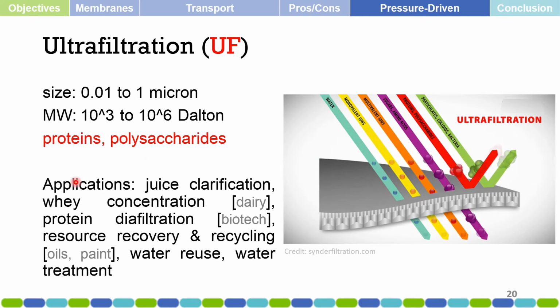Since ultrafiltration is quite costlier than microfiltration, ultrafiltration can only be economical when it involves heat and product recovery and water recovery, and when you are able to avoid additional treatment costs for the wastes. So you apply ultrafiltration in the process.